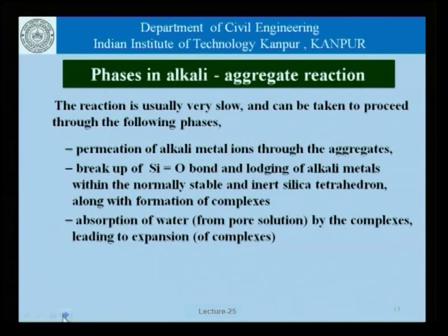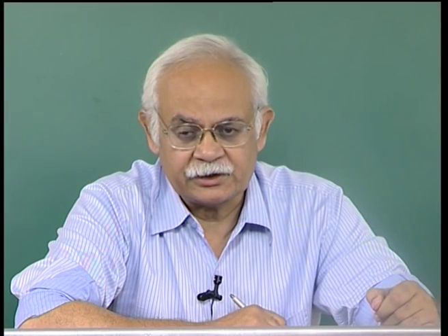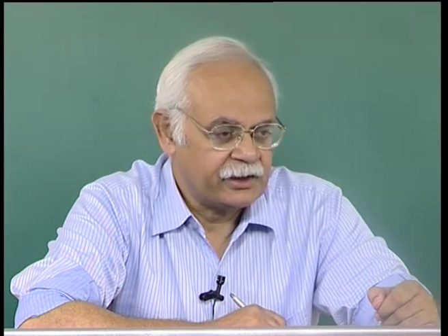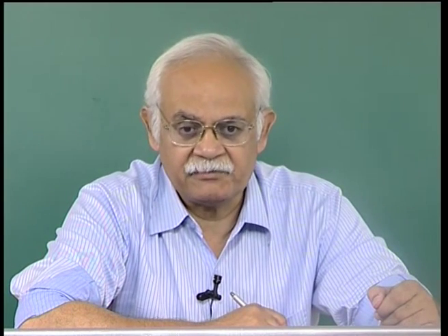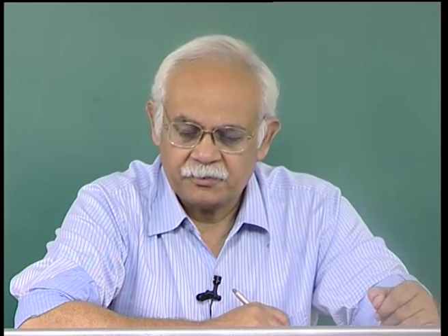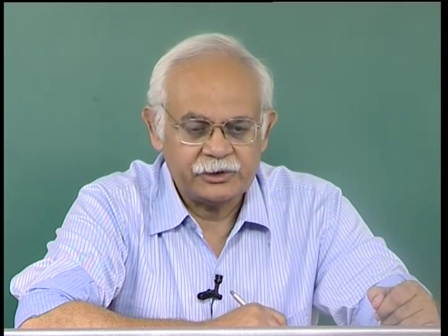Once these gels are formed on the surface or maybe inside the aggregate, they absorb water from the pore solution again, and this leads to swelling and expansion of these complexes and finally cracking of the concrete on account of alkali silica reaction. We must remember that water in concrete is available in plenty. It could be the water which is present from the time that it was mixed or cured, or it could be a replenishment by way of rainwater or any other form of water which is present.